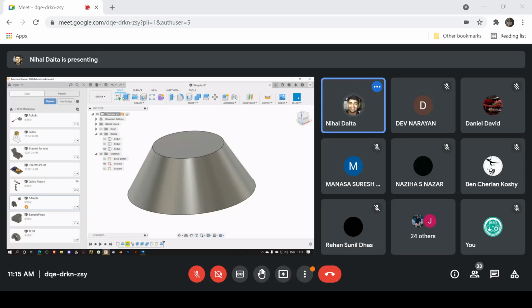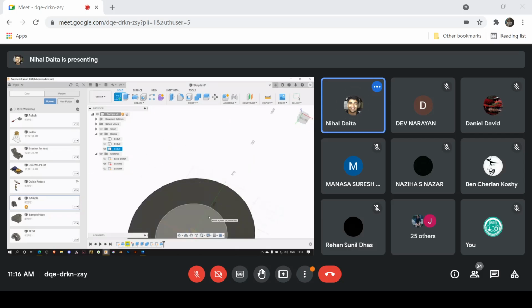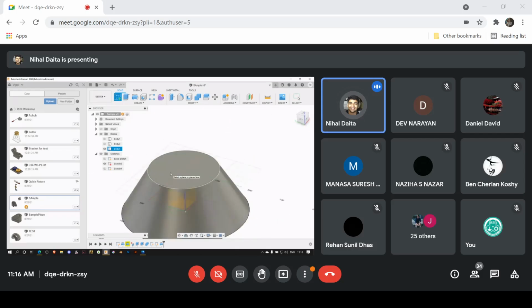There's nothing to it. So as you've seen earlier, you can create sketches on these primitive planes, right? As I've shown you, x, y, y, z, x, z, all that. And you can also create sketches on already developed planes or already developed surface, flat surface to be exact. For example, as you can see here, this is getting highlighted when I move my cursor over it. Same goes for the bottom face, right? This is because both of them are flat surfaces and you can use them to create your new sketch, right?